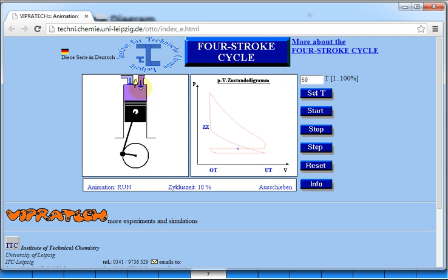This valve now kicked open. The exhaust valve is open. You're pushing it out. And then your valve closes. This intake valve opens. You're starting that intake stroke again. Notice the pressure is low on the intake. It's a vacuum. It's a slight vacuum in the engine, right? If you have a vacuum leak, okay, that's why. Air is getting where it shouldn't get into your engine. So you can trace this around. You see this is modeling a 4-stroke cycle, like an Otto cycle gasoline engine. And you could just watch this a few times and you'll see, okay, I got the picture.